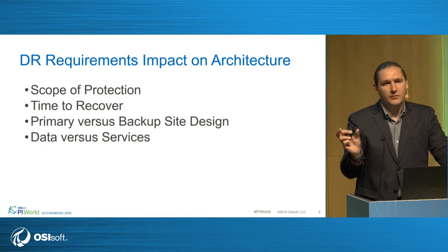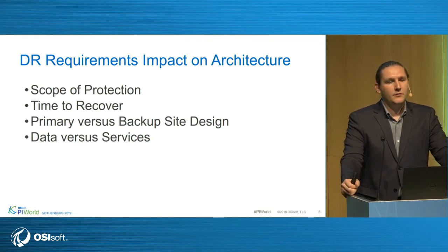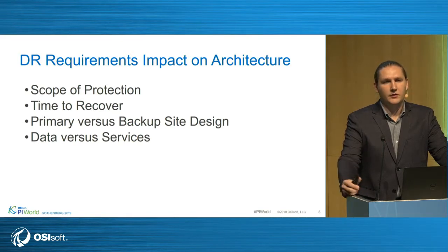So you will have a gap in the data during the emergency. But also, if we are using techniques like OPC HDA server, or on the data source level, we have the availability to have the history recovery. That's all. The whole gap can also be recovered.